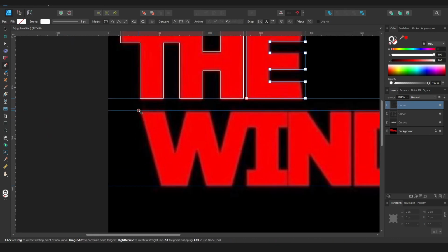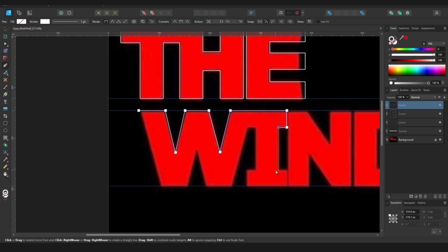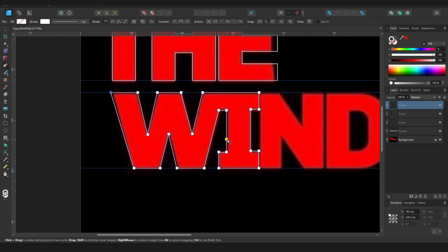This one I'm gonna do with the pen tool. So hit the P key and just kind of trace along this W. Since it's not as blocky as the other shapes, and I'm just holding down shift to get this to align to a straight direction. And then we'll go over here. And I'm just kind of doing this quickly because I'm going to fix all the shapes when I'm done anyways, so I'm not worried too much about things.